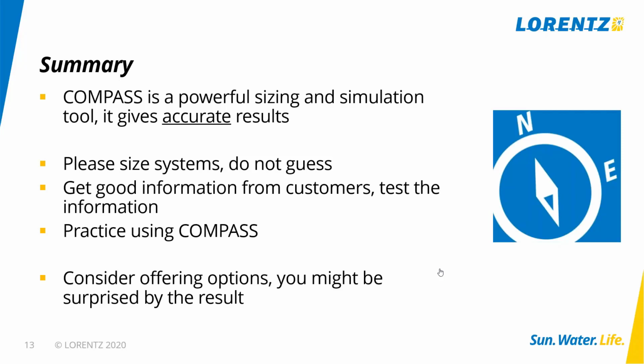Be really careful on things like people saying, well, we have a diesel pump that's 10 horsepower or gives me 100 litres a second, and then extrapolating that by 24. Please don't do that. Calculate what's the water required per day for the community, and then you're on a good place. And really practice using Compass. So don't be scared of it. You can't break it.